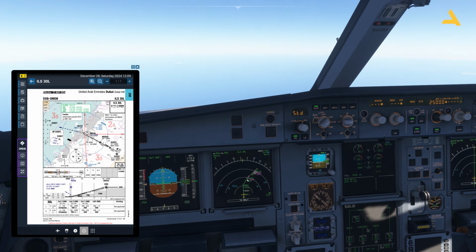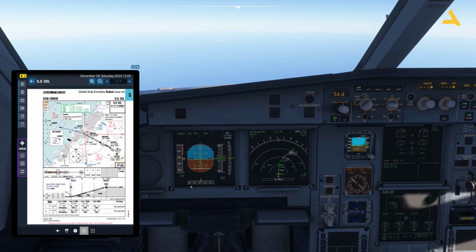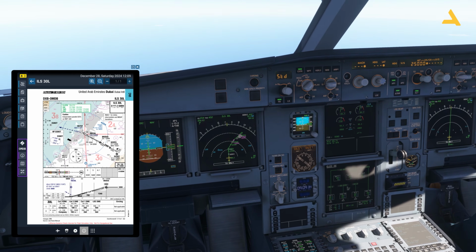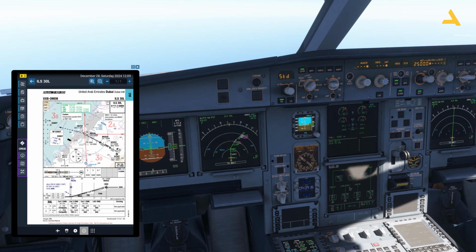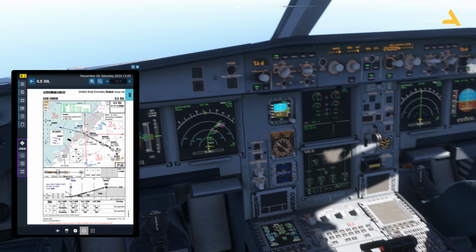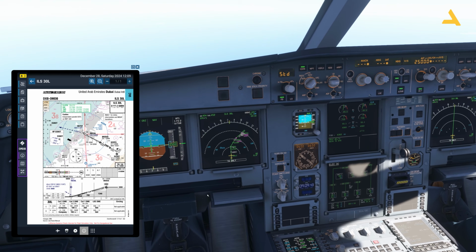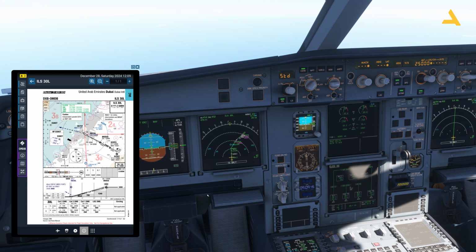So once you're near the runway, you will even start to see the distance over here on the primary flight display. Now for the category 3 DME, you have the settings in radio and baro. So there are two ways to actually get the minimums. This is actually an altitude at which you will be hitting this call out minimums, and you have to decide whether you want to go with the landing or not, because the instruments are aligning you with the runway and you're following the glide slope.